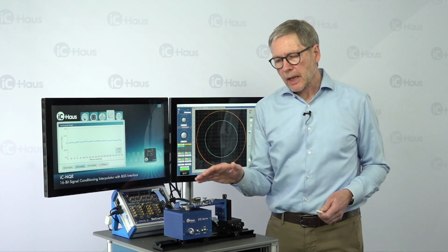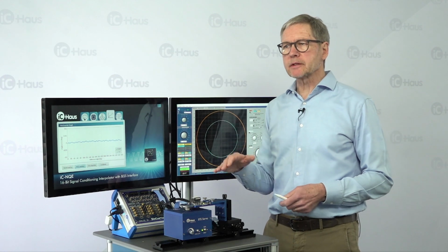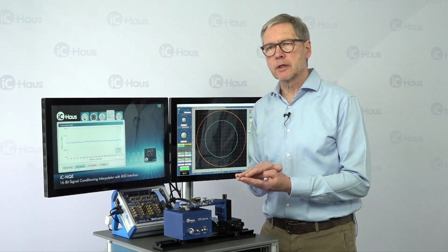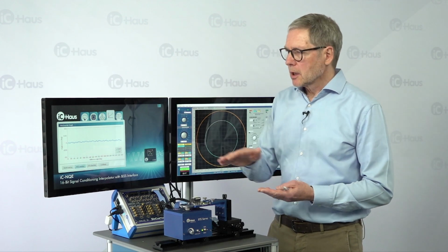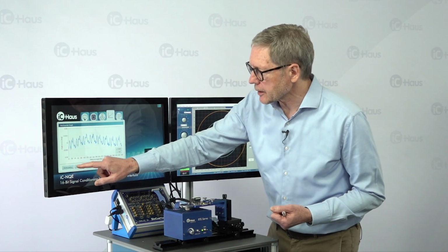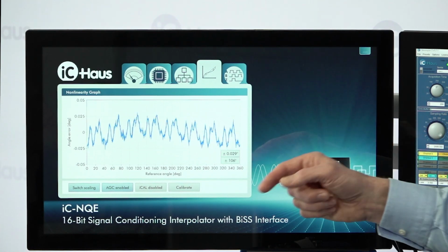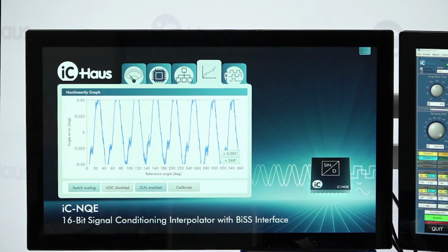Now, when you would like to get a noise-free input signal, you may like to operate the inductive sensor at a distance where it has not been designed for. In this case, you allow higher input distortion. Well, it's not fully visible here. Let me switch the scaling here. Now, that's a typical input distortion for this type of sensor if you go too close. But now, having this calibration feature, I can easily compensate this. So finally, we end up.